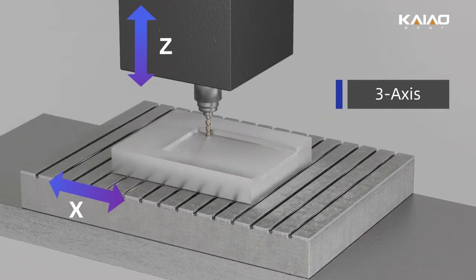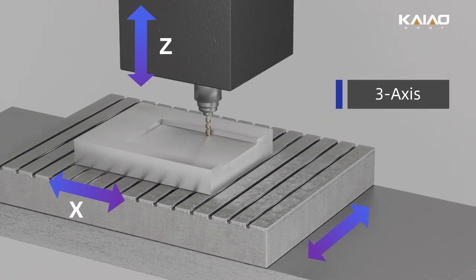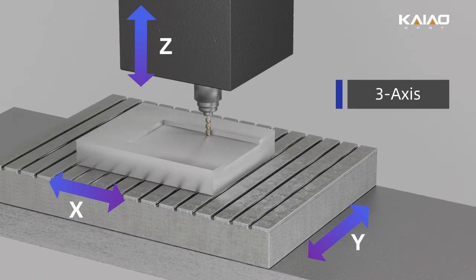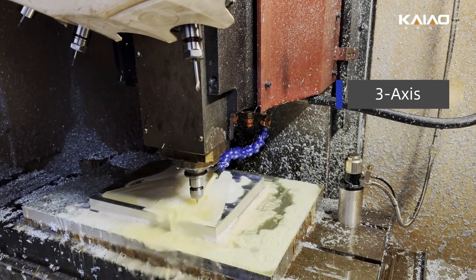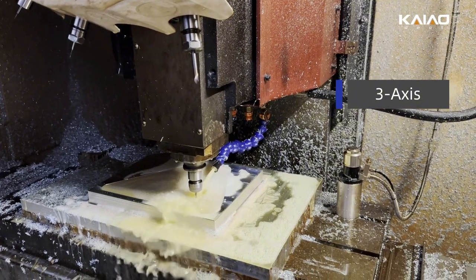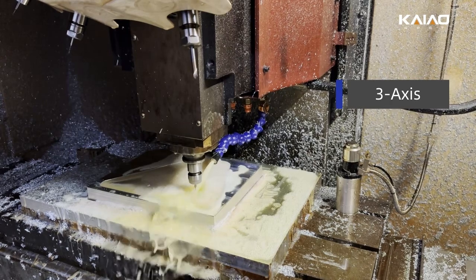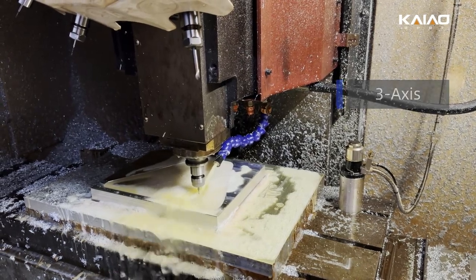With standard 3-axis machining, the cutting tool can only move along 3 linear paths, X, Y, and Z. Think of it like holding a pen perfectly vertical. Your hand can move up, down, left, and right, but the pen tip always points straight down. If you need to machine the bottom of the part, the machine has to stop. An operator has to manually flip the part over, reclamp it, and start again.